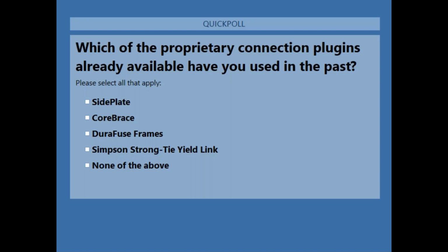Today we do not do that yet. That would still be up to the detailer to confirm that. Okay, good to know. So that's an area to be aware of, that you may need to adjust the length of those bolts to make certain that's meeting all the requirements we need.